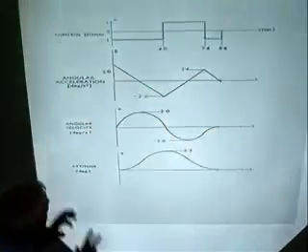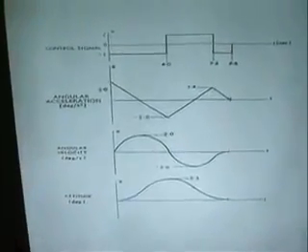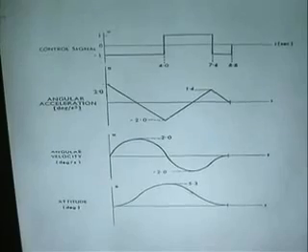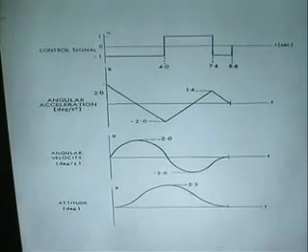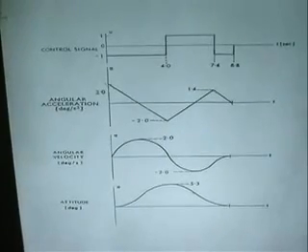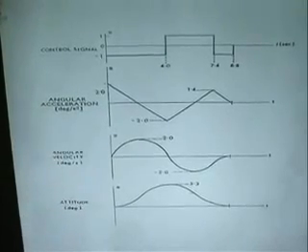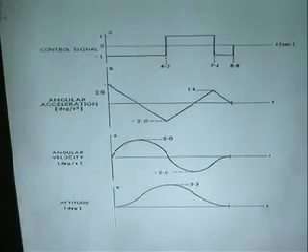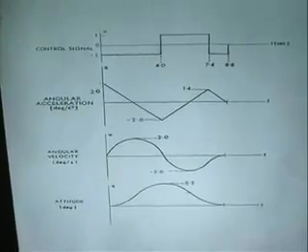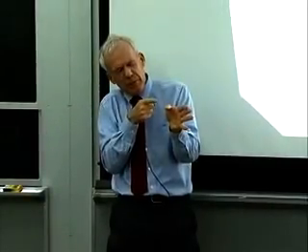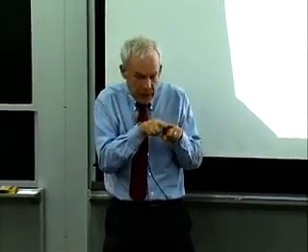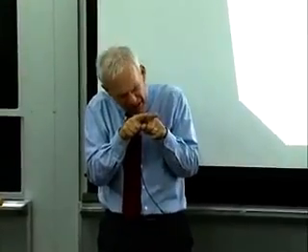The optimal control law in this third order problem is 3 periods of maximum drive on that gimbal angle, on that engine angle rate, which will take any initial offset, any initial condition of the 3 state variables, bring it to 0 in minimum time. And the particular one that was going to be of interest was not being able to align that engine perfectly through the center of mass at ignition. There was going to be a misalignment. The attitude error would be 0, the rate would be 0, but there'd be this misalignment.